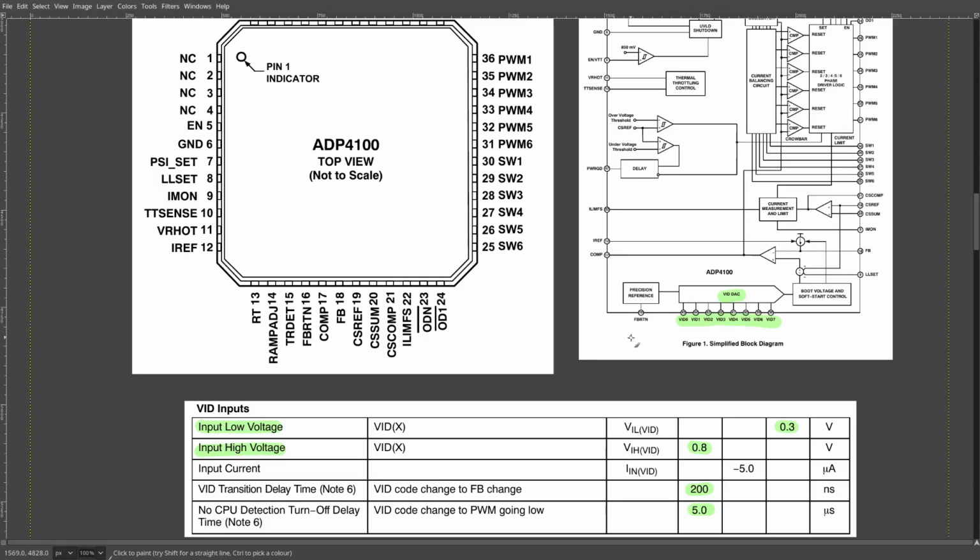In a lot of controllers where you see a voltage divider, it will have a single static reference voltage, like 0.8 volts, that you're dividing. Your divider will create a steady state where, when your output voltage is what you want, the feedback voltage will be 0.8 volts. The controller does everything it can to maintain that. We're doing a similar thing here, where feedback is being maintained at this DAC voltage. But because we can change this DAC voltage with the VID, that's how our output voltage changes.